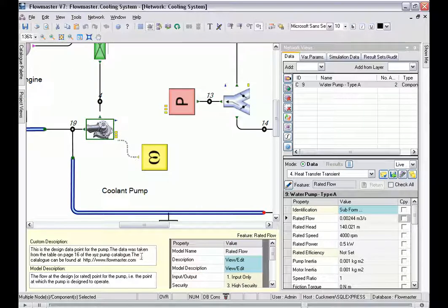And if we look at the pump in more detail, we can see that there are fields for extended properties. These are for your data or methodology statements, links to repositories for process rules, or any other use that you can define. It's also possible to define non-analytical fields, such as part number, weight, cost, lead time, manufacturer, etc. Security access can also be defined for this component, and this will be covered in a later video.